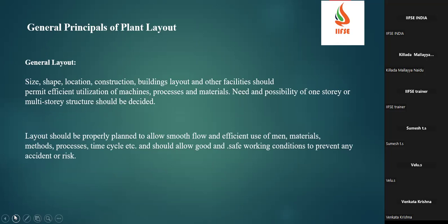So with respect to plant layout, what all is to be considered? If you see the general layout of the plant, we would have seen it in many places, or if you are already working, you will have your plant layout, showing the respective facilities or blocks which you have defined, like production, quality, R&D, utility, effluent block, office building or admin building, tank farm area, storage area, parking area, fire hydrant system or fire hydrant line, or pump house.